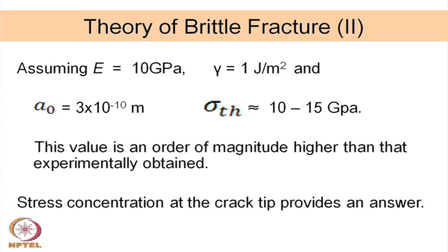The presence of a dislocation, a line defect, a defect in the arrangement of atoms, leads to the requirement of a lower stress for movement of the atoms. Of course, that was not a fracture, it was primarily plastic deformation. So, the presence of a dislocation explains why the stress required for plastic deformation is much less than the theoretical value.